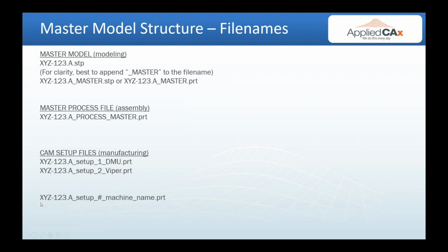So to bring it all back together, master modeling is basically a file management strategy. Wavelinking is a tool that you can use to sort of execute that strategy pretty easily within NX. And the thing that it enables you is basically you can create simplified models or modified models within a CAM setup without changing your master model very easily. So you click on Wavelink, you hide your original, you edit to your heart's content, and you make sure that you evaluate your CAM program against your master model, which always is living in your CAM setup file.